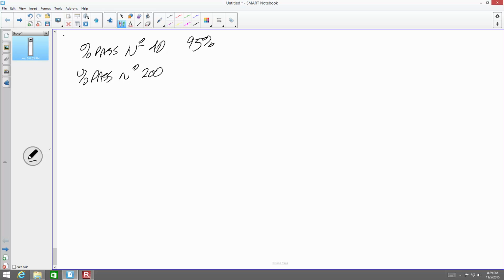The number 200 is 57%. Liquid limit equals 37. Plastic limit equals 18. What is the AASHTO classification?